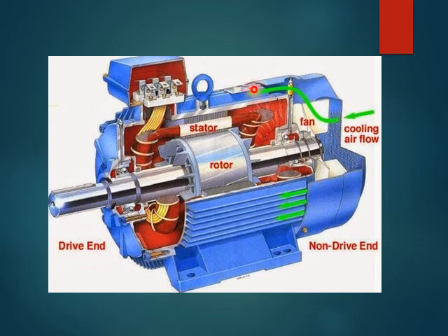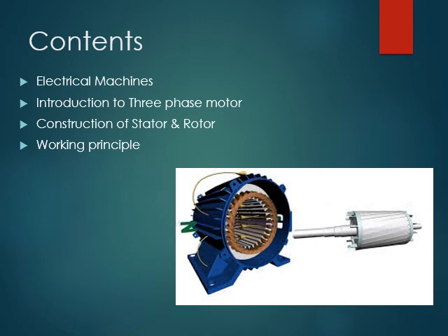You have some ducts on the stator frame for the cooling purpose, and we have three terminals over here to supply AC so that we can generate some constant flux. We'll see this for the next topic. Contents to be covered in this session are electrical machines, introduction to three-phase motor, construction of stator rotor, and working principle.